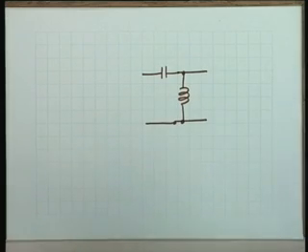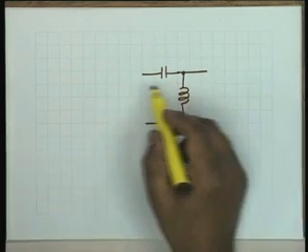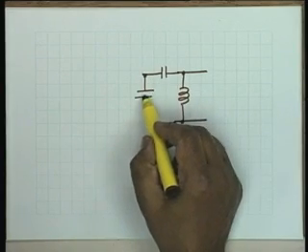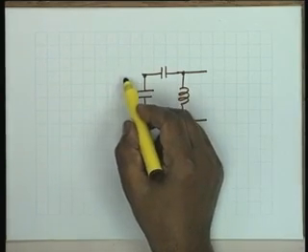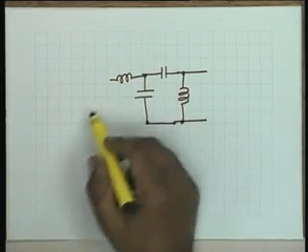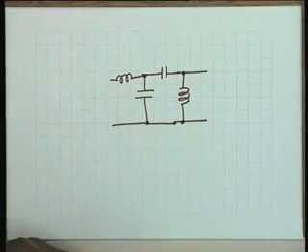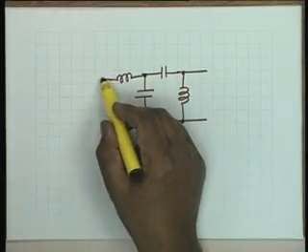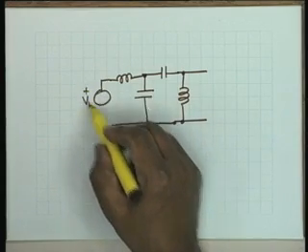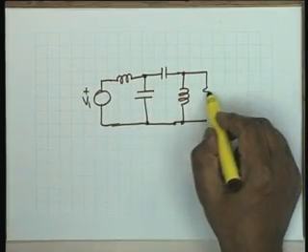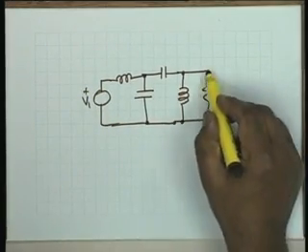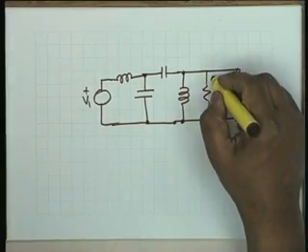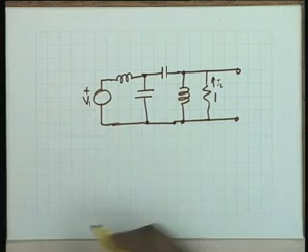Then the question of infinity. What should we have here? A capacitor in shunt and an inductor in series. The last element is a series element because of the voltage source. This is V1 and this is a termination of 1 ohm, and this voltage, I am sorry, it is not the voltage, it is the current I2, that is our concern.